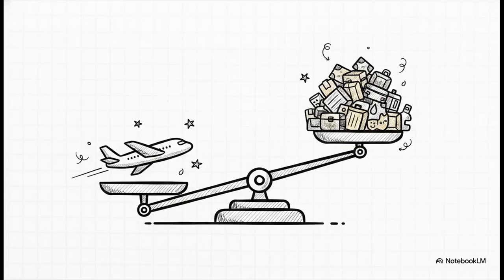By achieving this perfect mathematical balance prior to every single flight, airlines are actually doing two big things. First off, they guarantee that no matter when an engine failure happens, there's a safe, pre-calculated way out. Second, it lets them maximize their efficiency. By perfectly matching the aircraft's weight to the balanced field length of that specific runway on that exact day, they can safely load the maximum amount of passengers, cargo, and fuel without ever risking a runway overrun. It's safety and economics working in total harmony.